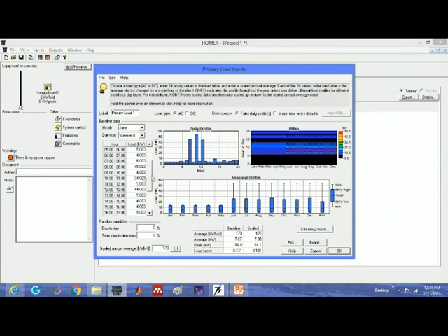See here at 10 to 11, I have given it 54. So this is my peak load. So I have to design the system according to the peak load, because at any moment we have to feed this 54 kilowatt. From where I am going to feed it, that is up to my application. I am going to feed it by solar panel, wind turbine, or something like batteries, whatever. That is up to you, how you want to make your system, right?